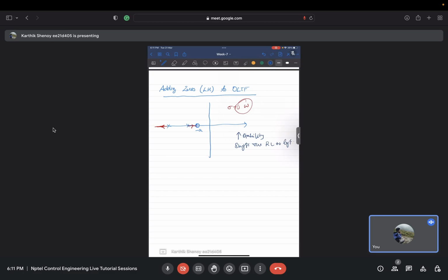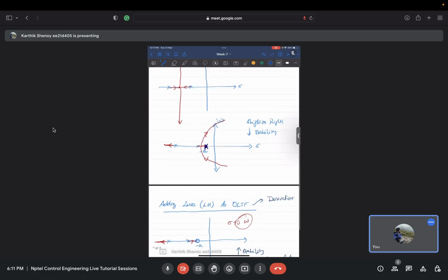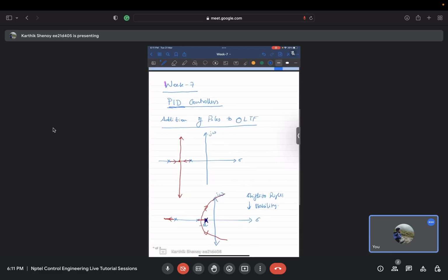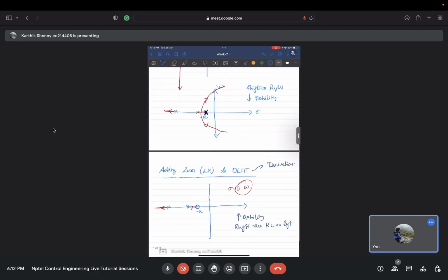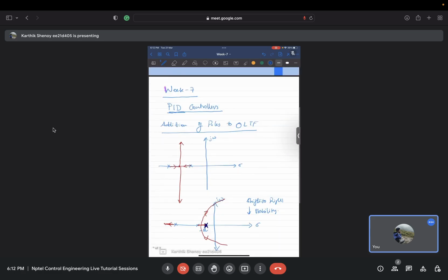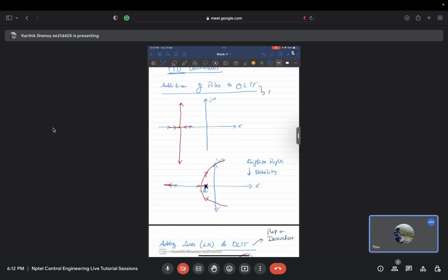Essentially, what you saw is a derivative, and A is the derivative control gain, or the inverse of the control gain for a derivative controller. This is not a pure derivative, because we are looking at the root locus, so it's proportional plus derivative, since we can always adjust the gain k also. And this is my integral.